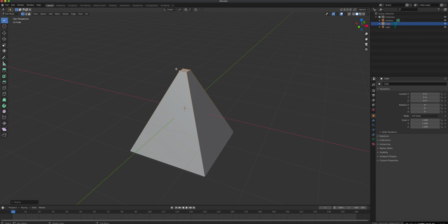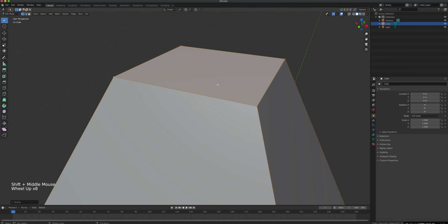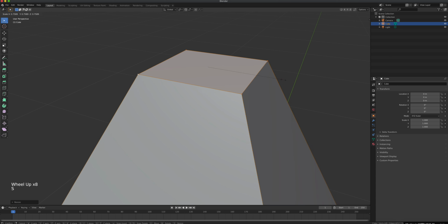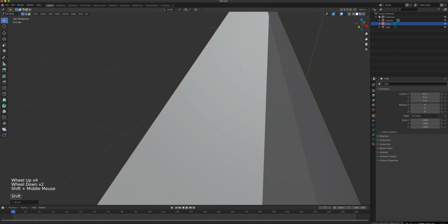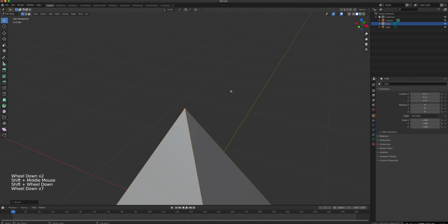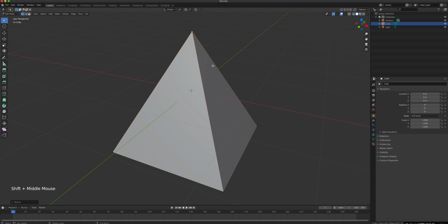And if you're not too sure about if you are converging right there, you can zoom in or you can dolly forward right there and then press S again. So you don't have to do scaling all in one time. You can stop and then get closer, and so on and so forth, right? Until, of course, your camera starts clipping. All right, so I just scaled those things, okay?